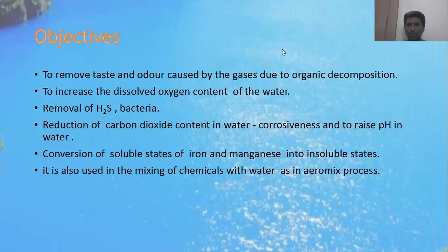taste and odor caused by the gases due to the organic decomposition. First, organic decomposition is mainly due to the presence of bacteria or viruses. Bacteria or maybe any fungi or algae utilize the organic matter present in the water, and upon their death there will be deposition, and the organic matter such as the dead or decayed parts of animals or plants will be degraded by the microorganisms.